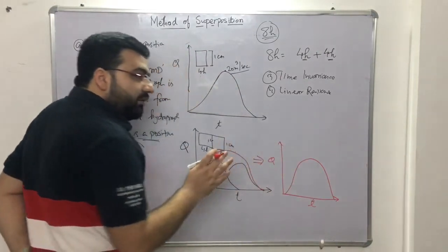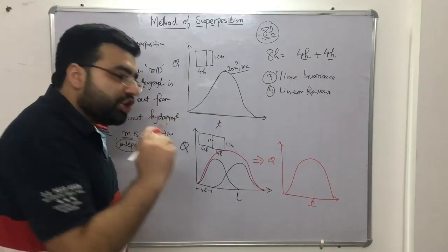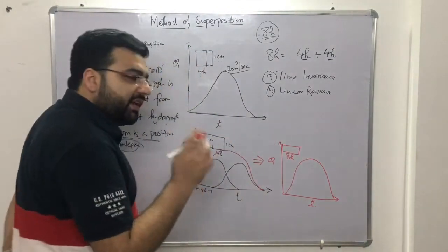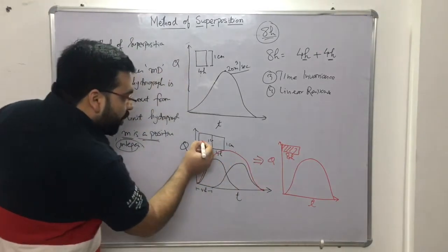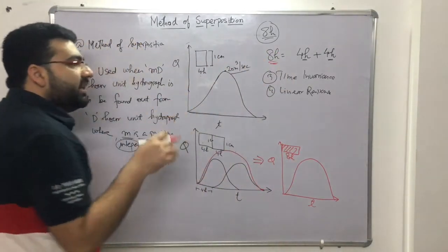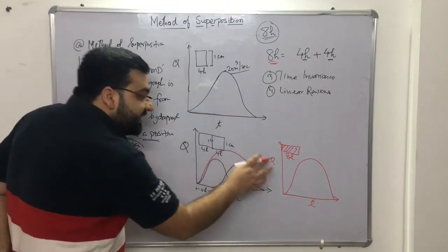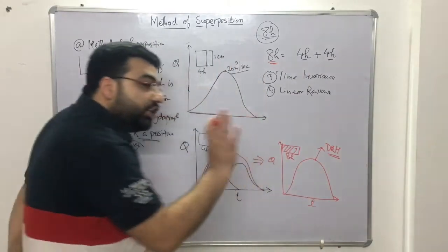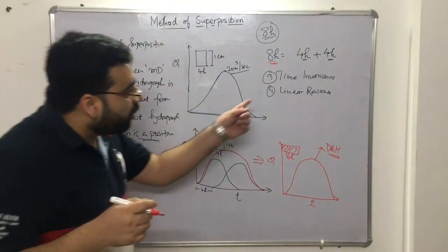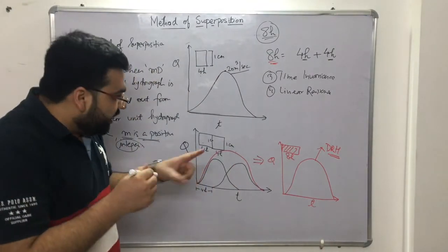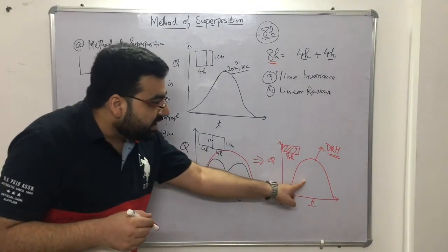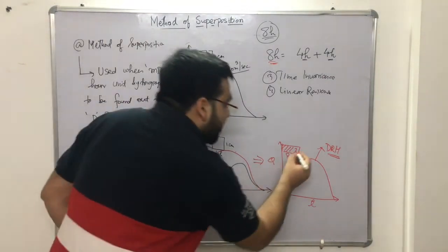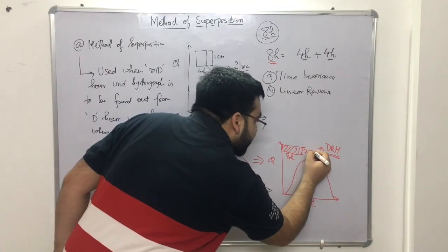Now if I write about it, what is the depth of rain, what is the duration of rainfall? The duration of rainfall will be 8 hours, right? Why? Because 4 plus 4 is 8. I needed to calculate the 8-hour hydrograph. But this is an 8-hour direct runoff hydrograph. This is not a unit hydrograph, because from the fourth assumption, linear response, if you are adding 1 centimeter plus 1 centimeter, this hydrograph will have an effective rainfall of 2 centimeter, not 1 centimeter. So you will have a depth of 2 centimeter.